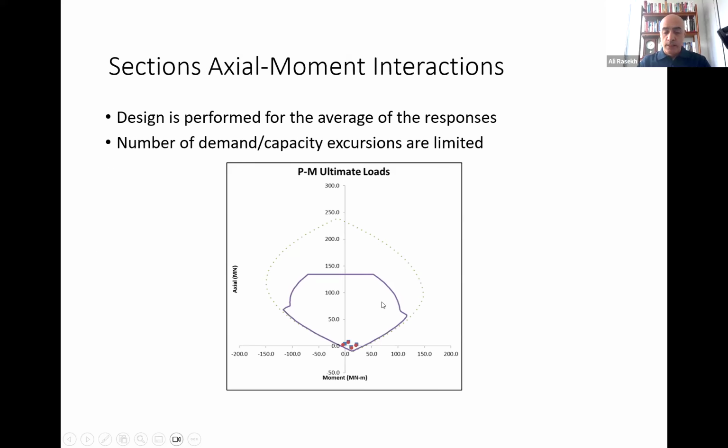Just some details of the interactions. We tried to make these steps automatic, so that the FEA program, Abaqus, creates the demand, and we compare it with the capacity per the interaction curves of concrete books, and make a decision about the design, whether we should make it thicker, or, a lot of times dimensions are set, and you should add to the reinforcement because it's a reinforced structure, luckily.